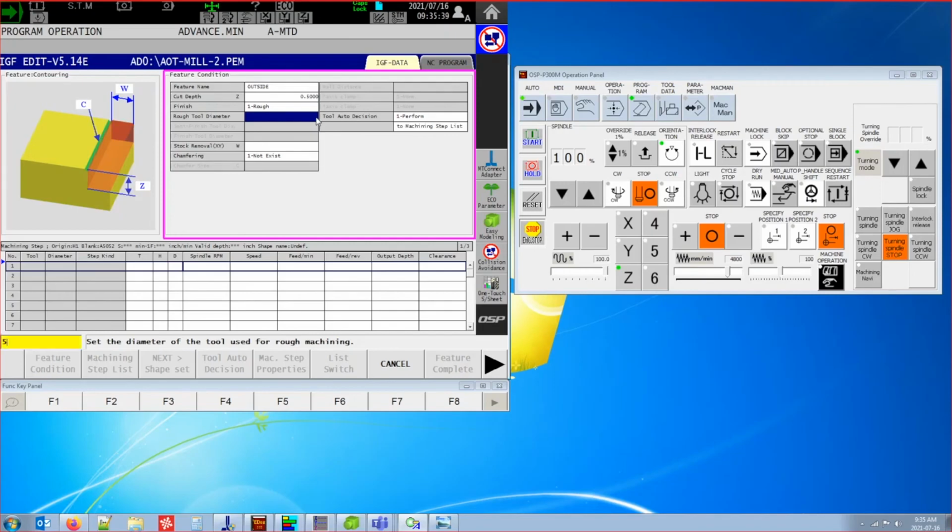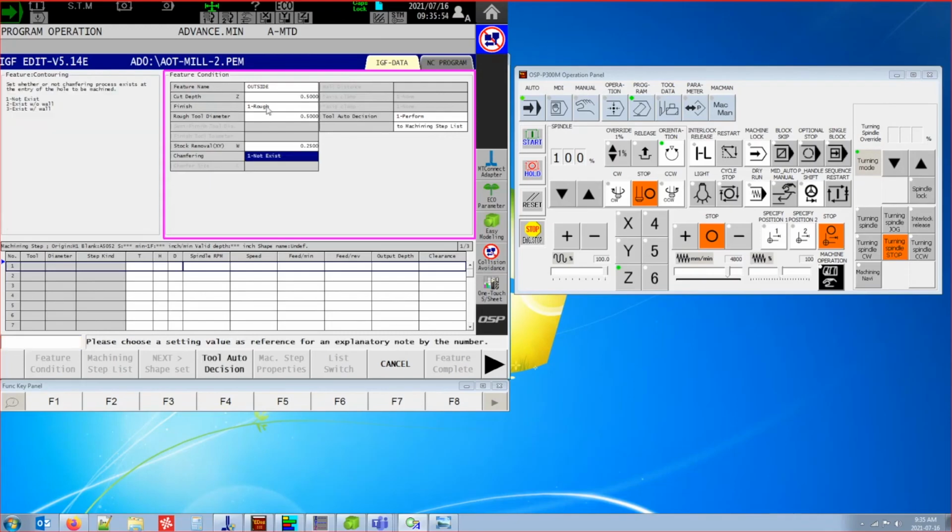Whenever I go into my tool diameter, I can tell it what tool diameter I want. I don't have a 5-inch end mill. I've got a 1/2-inch end mill, might be a little more appropriate. And this stock removal box is my width of cut. So with this particular cutter, whenever I'm machining inside of a simulator, I think 1/4 of an inch step over will do just fine.